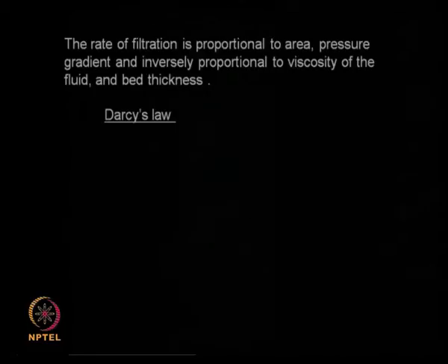So the viscosity of the fluid and the bed thickness contribute in an inverse fashion towards the rate of filtration, whereas the pressure drop and area of the filtrate contribute in a direct manner towards the rate of filtration.